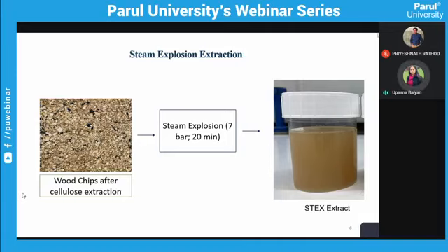Another process is to modify the membranes, and you can also optimize the operating conditions. What kind of operating conditions? For example, you can enhance the pressure or the cross flow velocity, but generally they will not play a very significant role in removing these fouling characteristics.